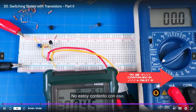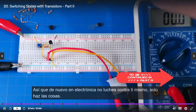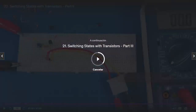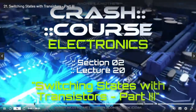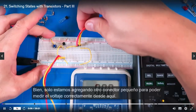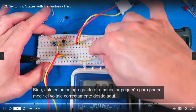Okay, I'm not happy with that. So again, in electronics, don't fight yourself. Just make it easy if you have to. What we're going to do is just add another probe. So we just added another little connector so we can measure voltage properly from here.